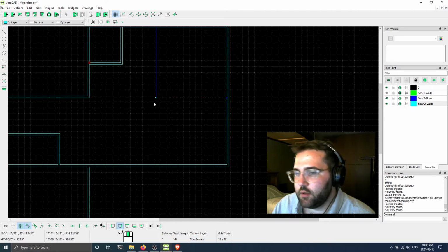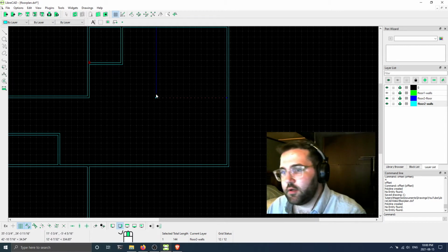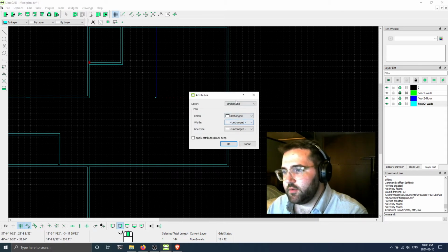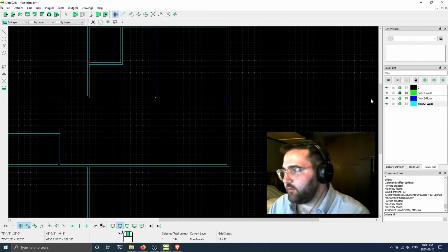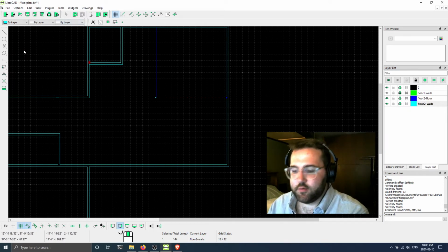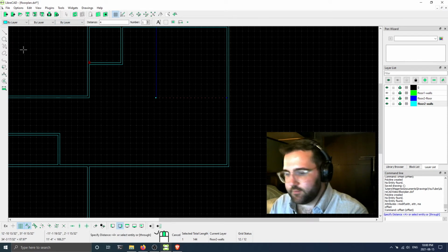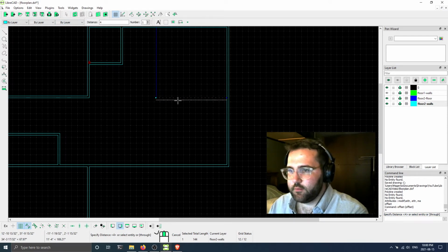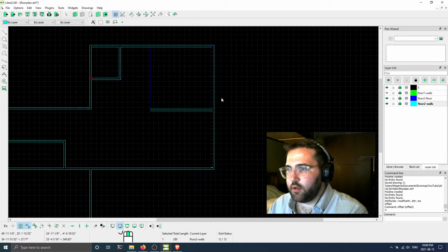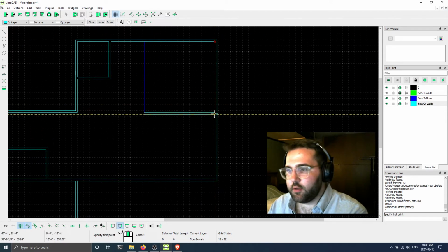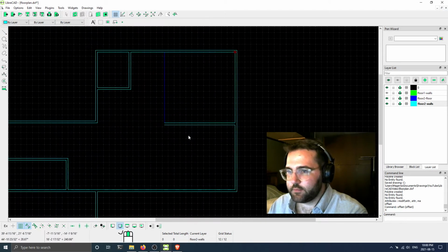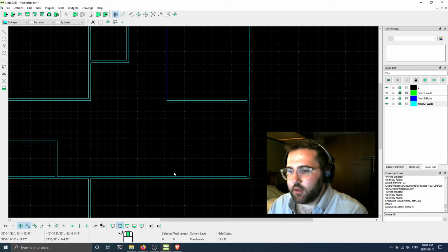So I can actually reuse this by, if I go into attributes and moving it onto my wall layer, and then I'll do an offset 4 inches. So type in the command line, and click over there, and then just clean this wall up by doing that. Do another 2-point line, and then I suppose you can just have the interior wall on this length.